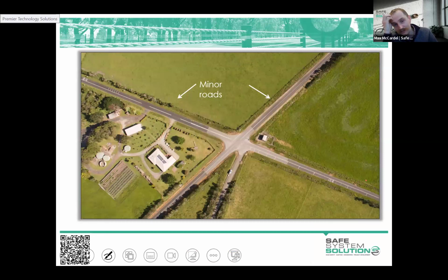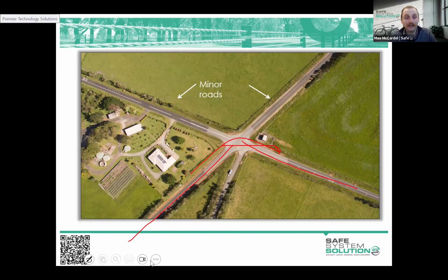All right, I'll show you this example of an intersection in a rural environment and some of the constraints this site has. It's a really strange configuration, because the arterial road is actually here, and then it bends and goes across there. So it kind of dog-legs, but it isn't set up to really support that. In other words, you've got a lot of right-turning traffic here, just because that's the dominant traffic stream. That's the arterial road.